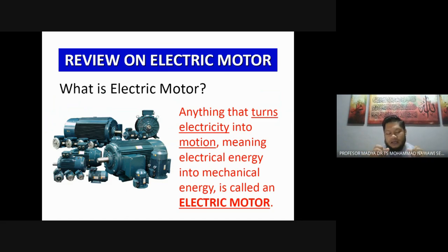You have to differentiate between mechanical braking and electrical braking. Mechanical braking is like a normal motorbike brake system, with the brake pad and the brake disc. That is something different. Now we talk about how you slow down the motor, or prevent it from going very high or in a reverse direction. This is known as electric motor braking.